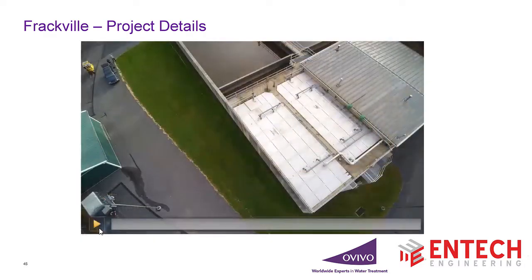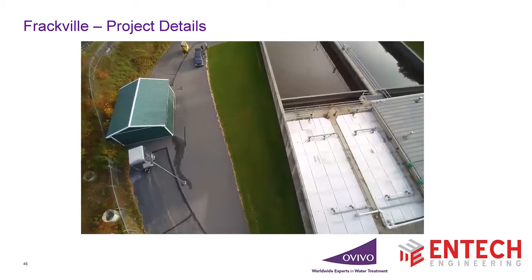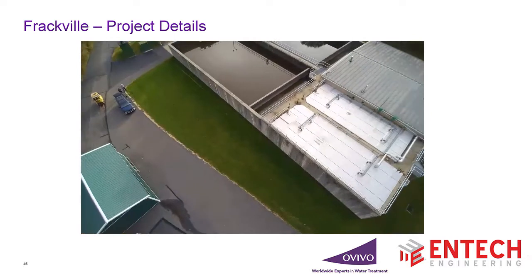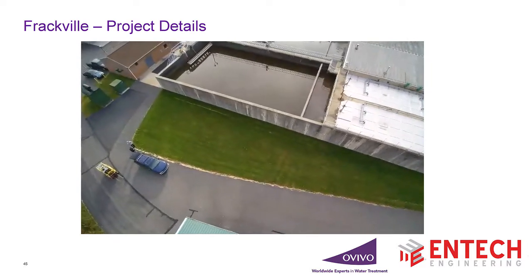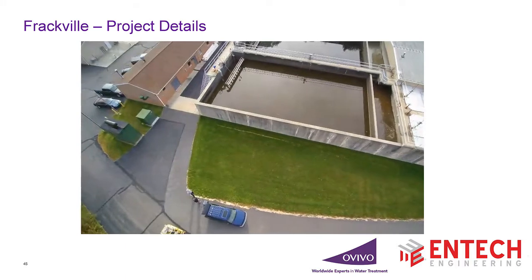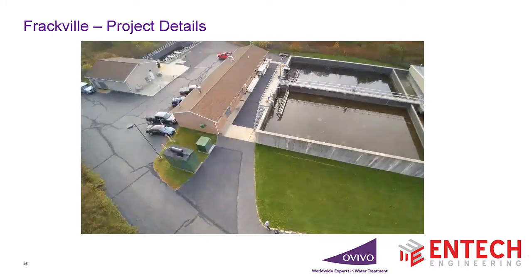And this is a picture from the top with the aluminum covers in place, the air distribution piping on top, and all those little black dots you see there by that air piping, that's the access to the diffuser. So even if you're completely filled with sludge and you happen to clog one of them, open up the top. It's just like cleaning out a gun barrel. Put the top back on and you're in operation. So you don't have to drain the whole process. You actually don't even have to shut the process down. Next one, Brian.